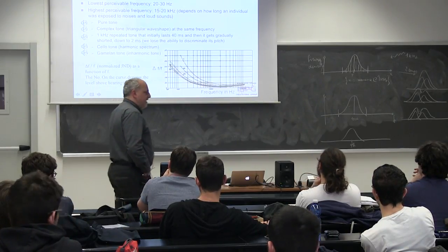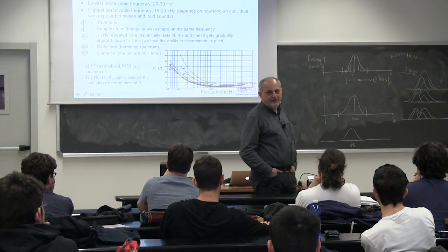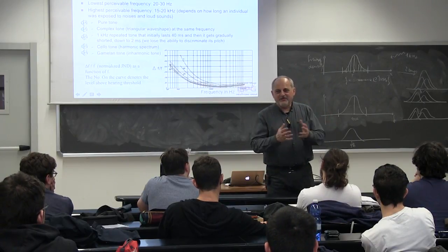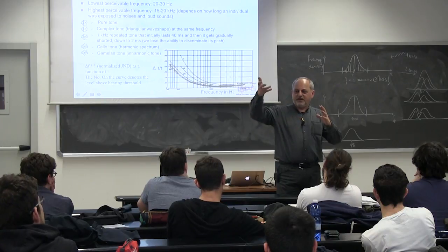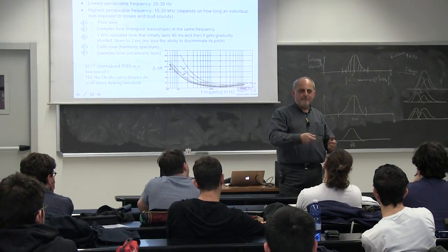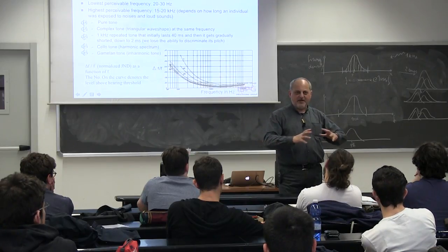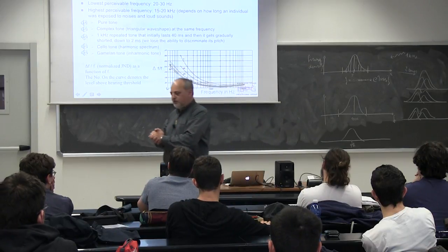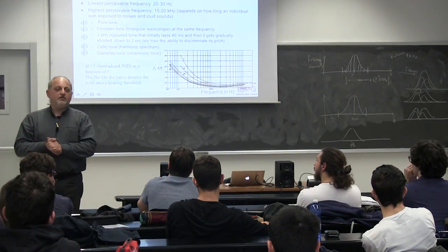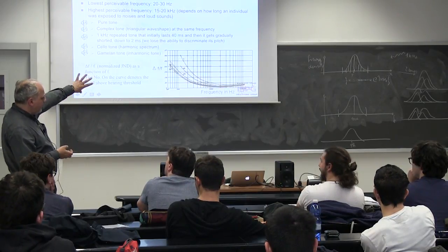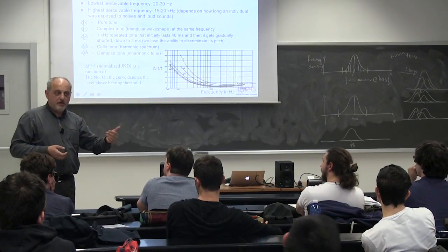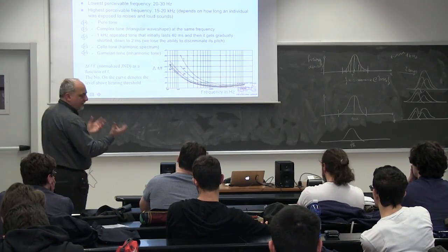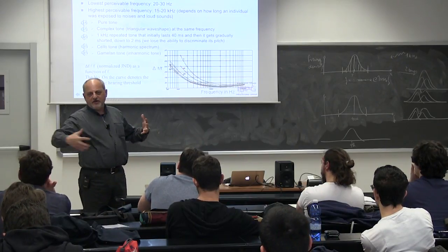The Gaussian function is an eigenfunction of the Fourier transform. Therefore, if you take a Gaussian and take the Fourier transform, you get a Gaussian. The only thing is that the signal will have a spread, and the Fourier transform will have the inverse of the same spread. So if I spread it out and make it wider, it will get narrower in frequency. Remember that Gaussians are quite important. If you look at the frequency response, you have a bell-shaped function. The impulse response will still be a bell function, more or less, so it will have a duration. That duration is sort of an integration time.